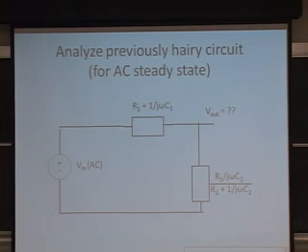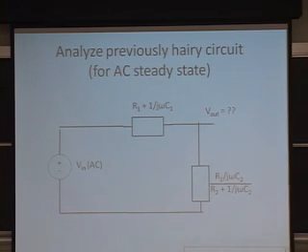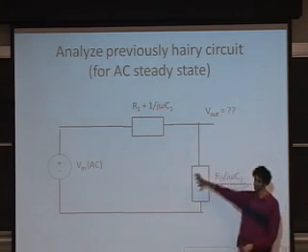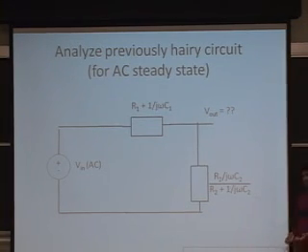Yes, that's a very good point. That's a great question, because it brings up the important fact that when omega is 0, your frequency is 0, you're at DC, and at DC, the impedance of a capacitor goes to infinity. An infinite impedance is an open circuit. Conversely, the impedance of an inductor is j omega L. So that implies at DC, 0 hertz, when omega is 0, the impedance of an inductor is 0. It's just a wire at that point, a short circuit. And so this perfectly matches with the steady state analysis that we did on Wednesday and on Monday.